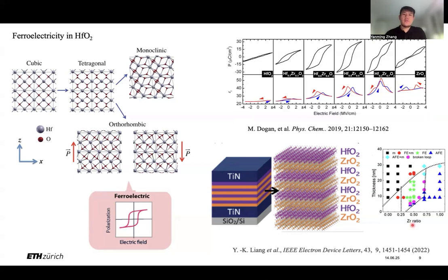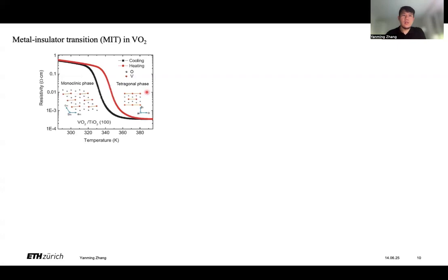One most recent approach, instead of making solid solutions, is making HZO superlattices, which is an alternating stacking of hafnia and zirconia atomic layers. In our group, we focus on the HZO superlattice in this work because it could potentially offer high temperature stability and polarization. Next, the Mott oxide we chose to study is vanadium dioxide, VO2, which is a strongly